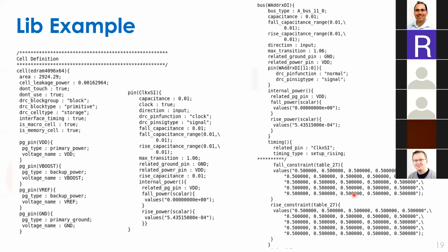So if you have just a generic custom block that does something that's not a standard cell and not a memory, you can define test benches and so forth, and it should be able to extract and write out your lib file. So if you can get the tools to run, or write your own tool, because sometimes it's even easier to do that since the tools don't seem to work too well, then that is something that can be done rather than just doing what Odem's showing here, which is writing it basically by hand.